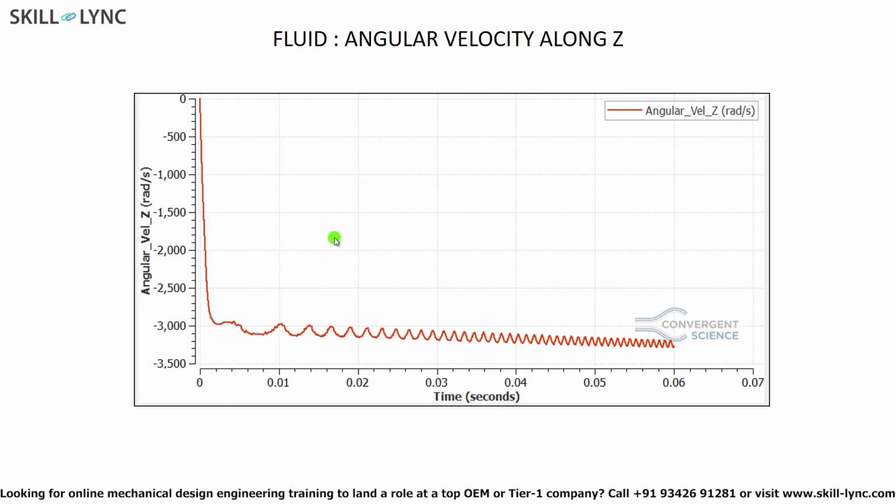Now one of the things that you need to look at in these type of simulations is convergence. So here we are running a simulation for about 0.06 seconds, and you can see that the fluid angular velocity has almost converged. But it's very important to not get fooled by this plot and many such similar plots.